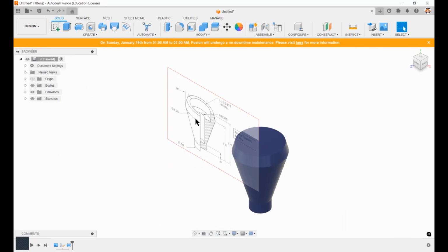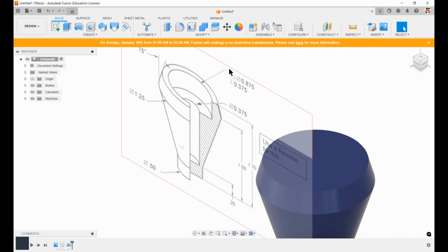Well, I got to put this centerpiece in here. All right, this center cutout. So that is just a hole because this little symbol right there is telling me it's a counter bore. It's telling me how big the counter bore is and how deep it is. Right? I can also see this center hole right here, and that's telling me that is 3.75. And that goes all the way down until it's a 0.25 from the bottom.